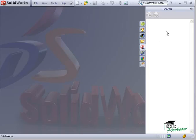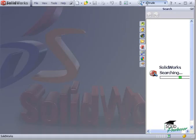If I expand it, you can see that there's nothing in it yet, and that's because this tab only works alongside the SOLIDWORKS Search Assistant, and that's found in the top right-hand corner of your screen. Once I type in a keyword and press Enter, the Search Assistant looks for all files that meet the search criteria, and the results are then displayed in this section.